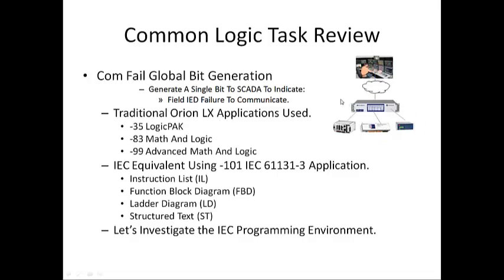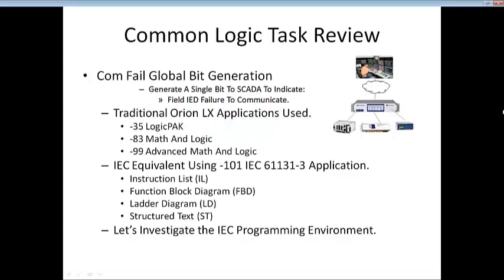Traditionally, we perform this aggregation of data utilizing -35 Logic Pack, -83 Math and Logic, or -99 Advanced Math and Logic. Within our webinar, we shall illustrate the various languages, capability, and methodology to perform the global bit generation as we would have done in our traditional Orion logic packages. So each one of the IEDs, if it does not communicate, will create a bit status for COM fail, and we're aggregating all of the COM fail paths and creating a general bit to be sent to SCADA, which would be a general COM fail. Back to the programming environment.